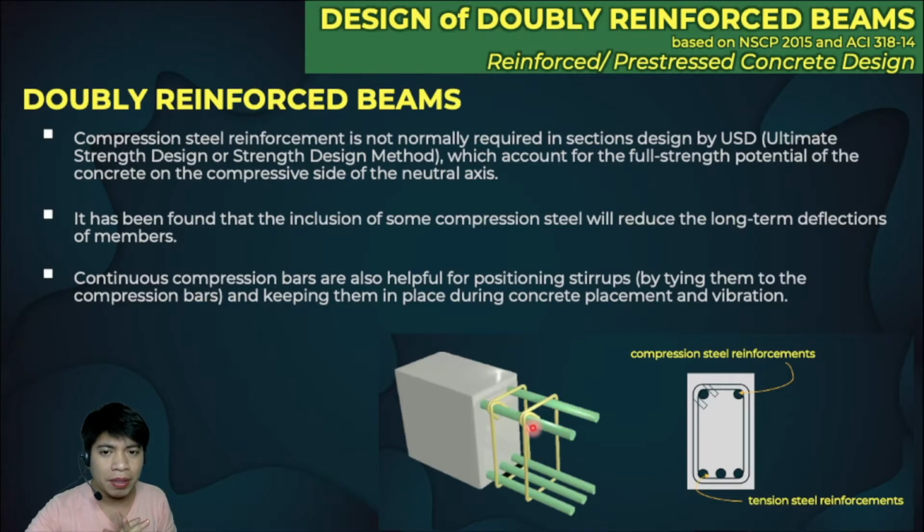Okay, so take note lamang guys, na kahit i-design natin yung ating beam as singly reinforced beam, for example, na-design lang natin siya na meron tayong kailangan na tatlong bars sa tension side. So take note na kapag kinonstruct na natin yung ating beam, kailangan natin maglagay pa rin ng dalawang bars dito sa ibabaw. Ang tawag natin dyan is hangers, dahil kailangan yan para makakapitan ng ating stirrups.